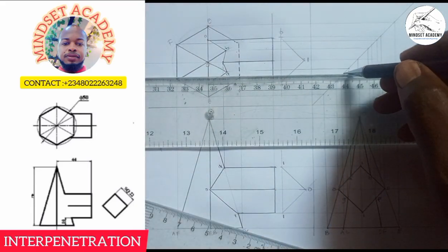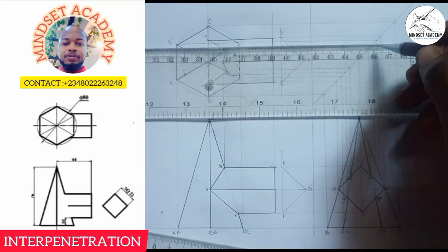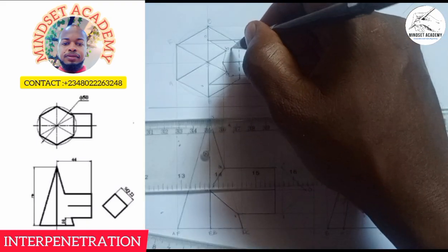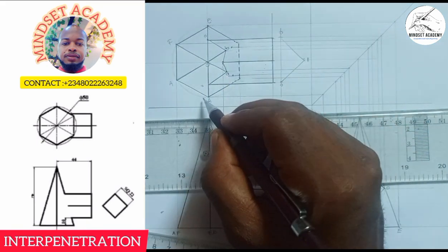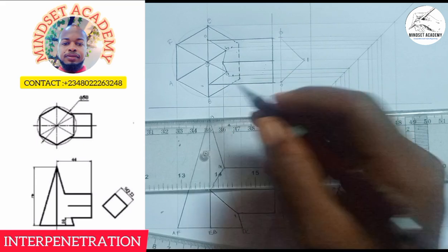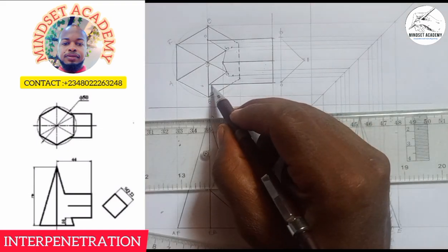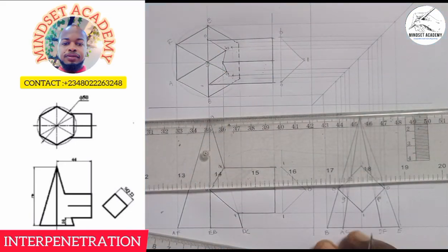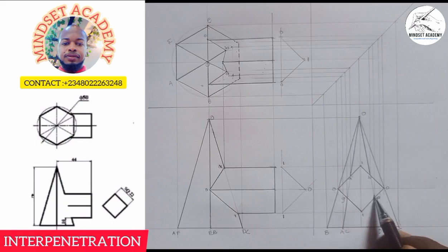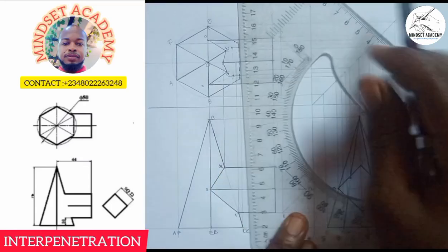So where G is meeting this point here, the diagonals, that will be a point. And also where F is coming here to meet the diagonal, that will be another point. This is the diagonal, this line you see is meeting it here, and this line that's coming meeting here. So this will also be a hidden line. All together, it will be a hidden line. So everything will come and touch here, these two, this way, here this way, and here this way. So let me break it out. And they are all associated to this, just like this associated to this, this also associated. So this point here, I'll take it up this way, touching here. That is what my line will look like.